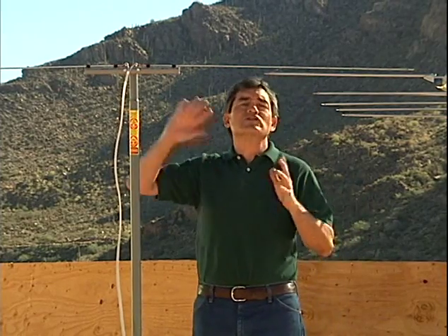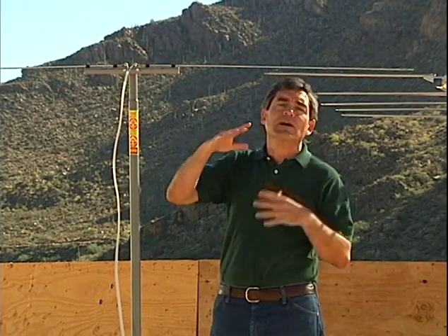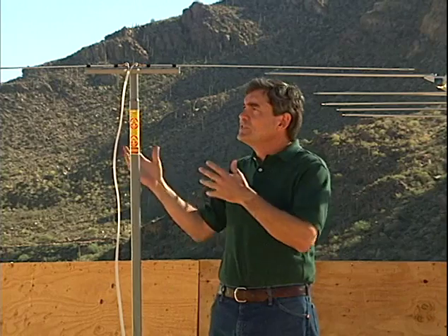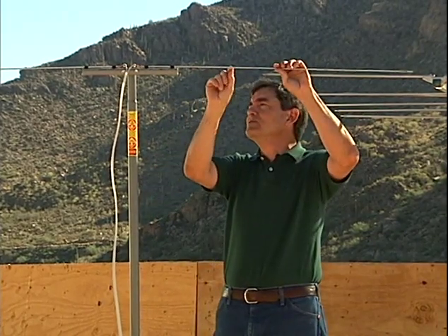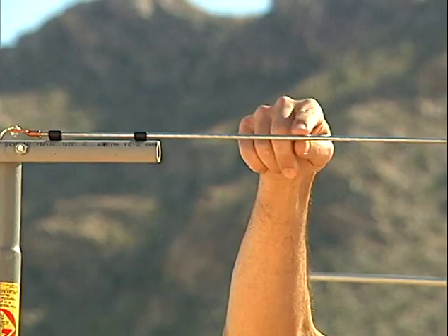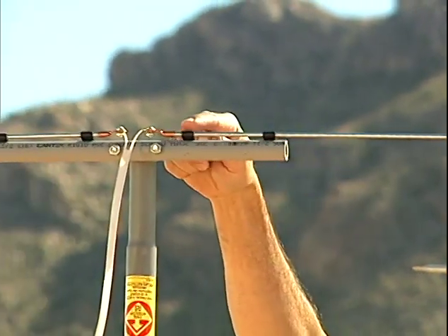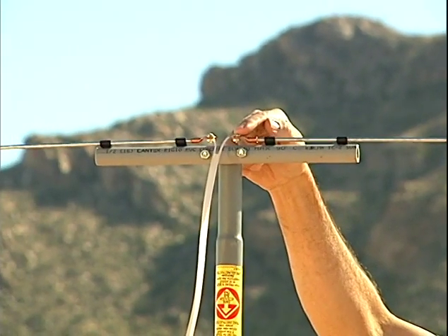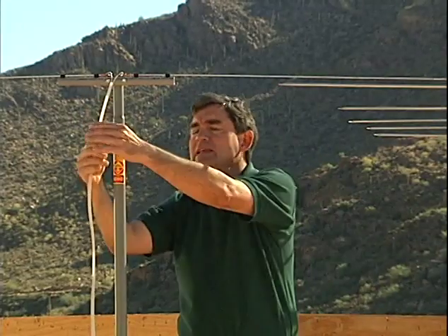And TV antennas work just like all antennas, by capturing a very small amount of the arriving electromagnetic field transmitted by the broadcast antenna that just happens to arrive at the receiving antenna location. Now, the arriving field will cause electrons in the metal elements of the antenna to vibrate a very small amount at the transmitter frequency. This generates a small voltage between 100 and 1,000 microvolts at the antenna terminals. This is carried by the connecting cable down to the receiving equipment.